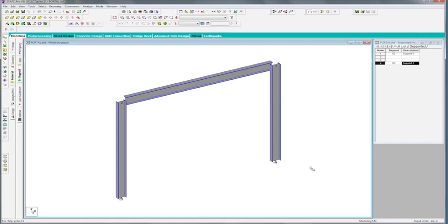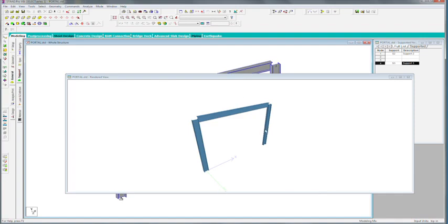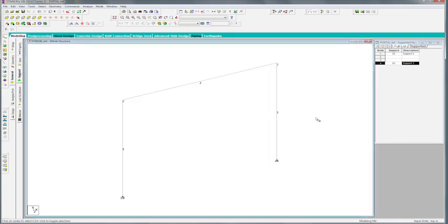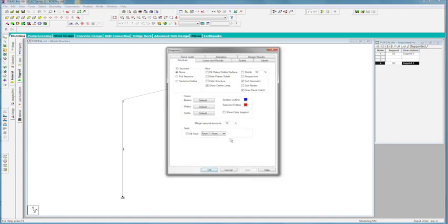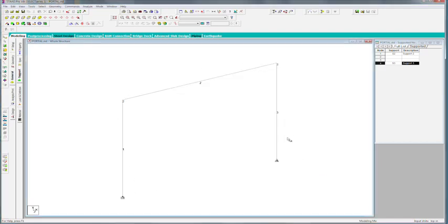We can also get a full 3D rendering at any time. Simply right-click and come down and choose rendering, and it'll render a perspective view of which then can be disposed of as a normal image. To get back to our normal view, as you see here, just simply right-click, go to Structure Diagrams, and click None and OK, and you'll be back to our analytic model.